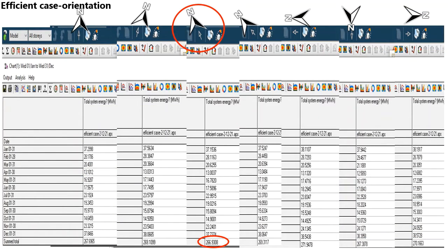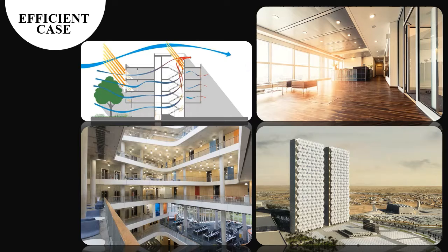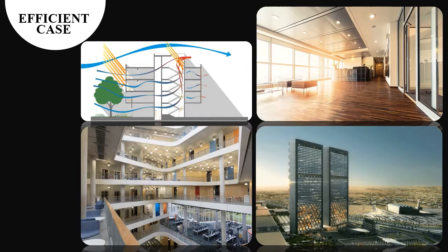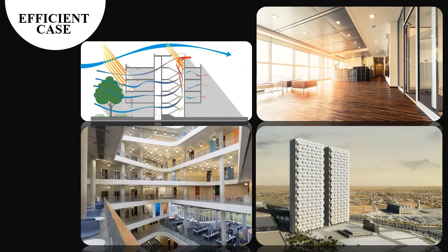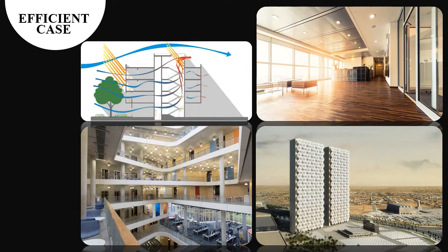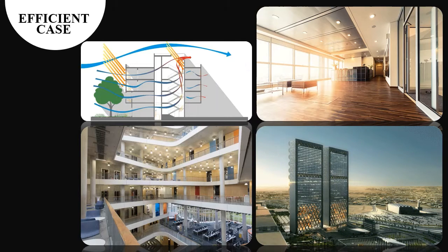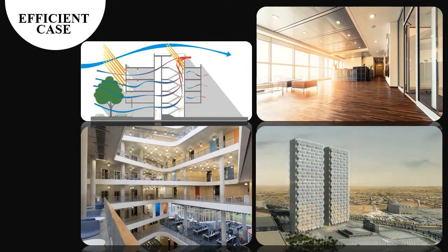To reach the maximum energy efficiency, we assess different orientation of the building. The Passive House Regulation, the atrium will increase daylight factor inside the building and enhance the quality of air by increasing the movement of the air. More glazing in the facade will participate in daylight enhancement. However, this will increase the glare issue and solar gain during summer. That's why we have the necessity to use the kinetic shading elements.